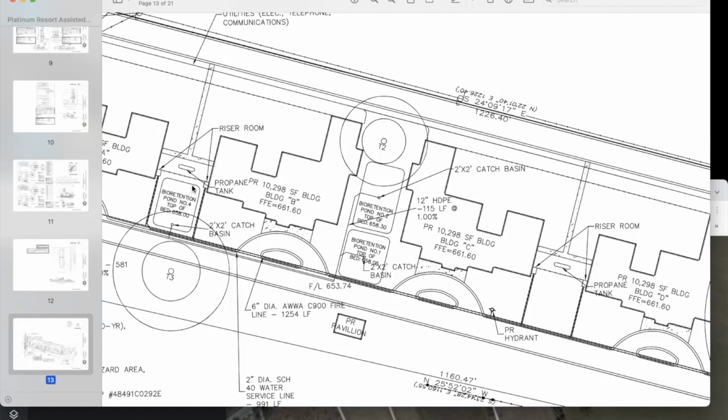That's what these are. And essentially, the civil engineer looked at the landscaping and said, okay, we're going to design the road and the buildings to catch that water and bring it to these things. So if it's going to land on the roof, then it's going to go into the rain gutter, and we're going to put the rain gutter in a certain way to direct the water towards this. And then same with the road, it slopes towards these things.